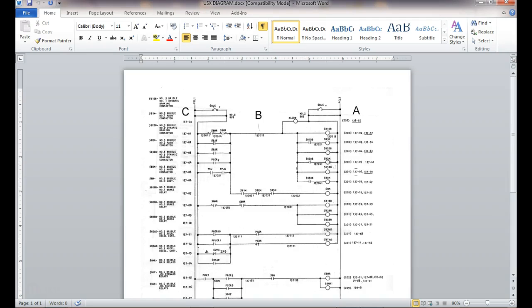Now look how many outputs this guy here has. So this rung right here has 1, 2, 3, 4, 5, 6 outputs. Right? But every one of them are on a different line number. Now here we got a line number that's stuck out here in no man's land. It looks like it. But this guy right here lines up in that plane, right? Understand that? So every line that's in the same plane gets the same number.